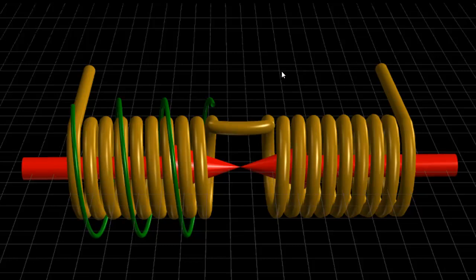If we put a load on this coil, and say that load had an internal resistance of, say, 3 ohms, then the 3 ohm load resistance would reduce the current flowing in this coil. And remember, I equals V over R. So if we increase R, then the current will reduce. So this is something that we've got to start thinking about.